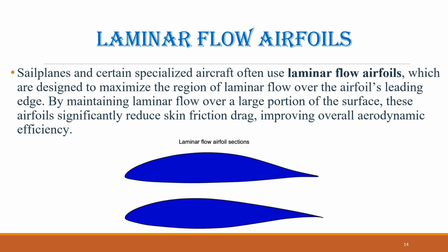However, there are trade-offs. Laminar flow airfoils generally produce lower maximum lift coefficients, meaning they tend to stall at lower angles of attack compared to conventional airfoils. They are also extremely sensitive to surface conditions. The airfoil must be glassy smooth and free of imperfections such as dirt, bugs, or fingerprints in order to achieve the intended low drag performance. Despite these challenges, laminar flow airfoils remain an important design choice for sailplanes and other aircraft where minimizing drag is essential.